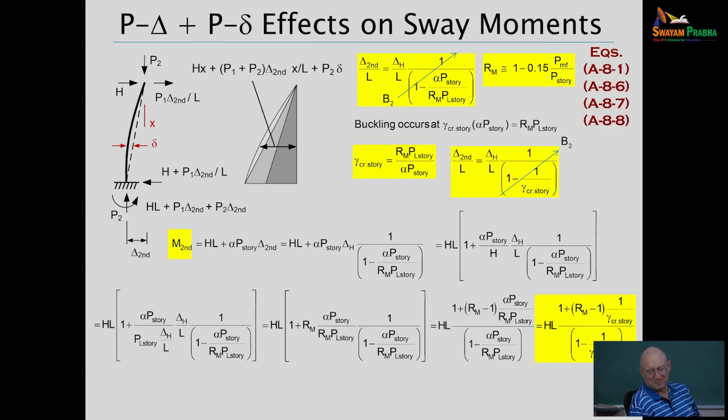Yeah, the sine curve. We did make the approximation to derive the C sub L. We needed a function for the deflected shape to get a small delta. So we basically took the buckled shape form. But that's a reasonable assumption, right? Yeah, reasonable assumption. The R sub m is a gross approximation.